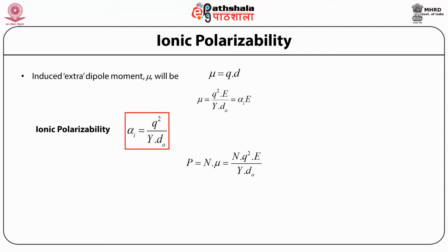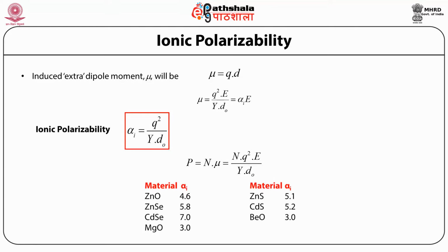For example, in calcium fluoride, that is CaF2, a material used for making lenses for lithography machines, the dielectric constant is approximately equal to n squared. So this enables the lens to be made with dimensions of about 0.1 micrometer. Students, you can see the following table showing the values of the dielectric constant of some materials where ionic polarizability contributes in addition to electronic polarization.